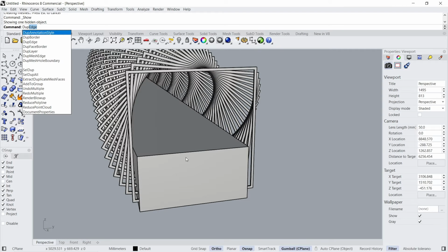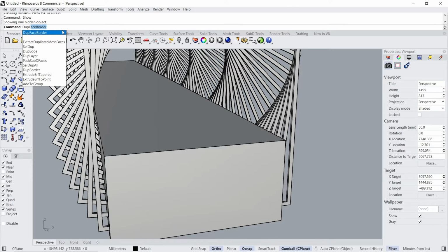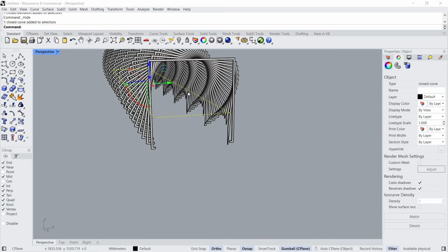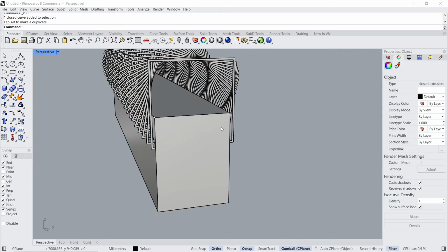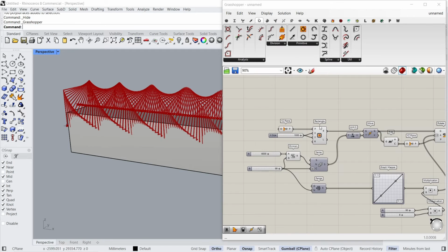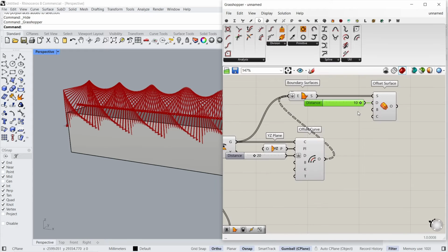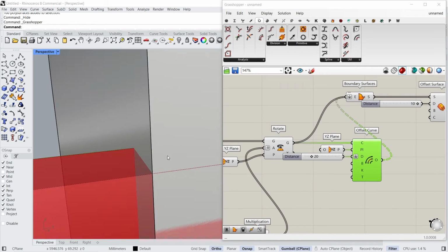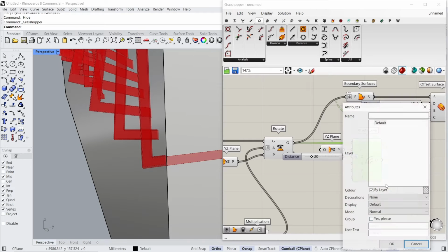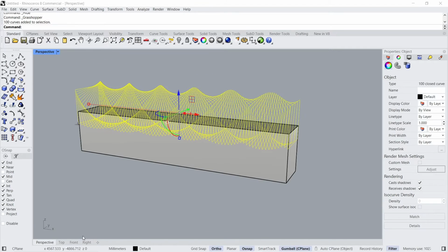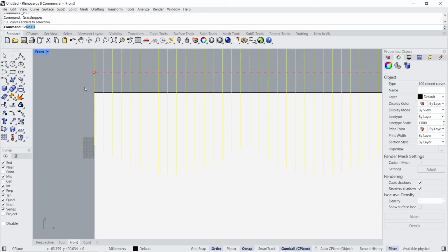Now I will create the same box again and hide the other objects. Open Grasshopper again. Bake these rectangles. I will create a surface by using them, but first, I need to scale them on the x-axis. Scale 1D.